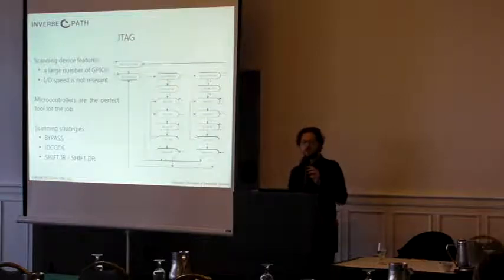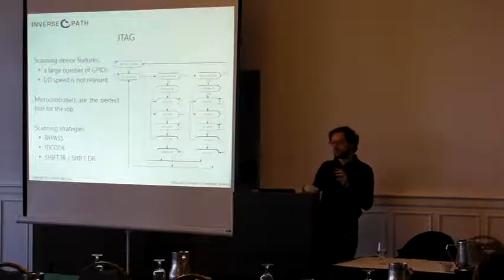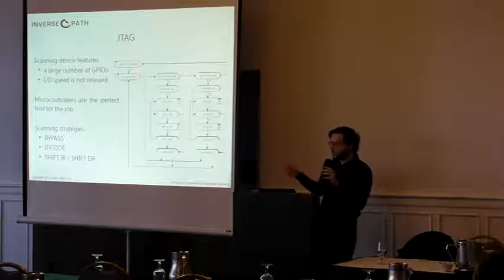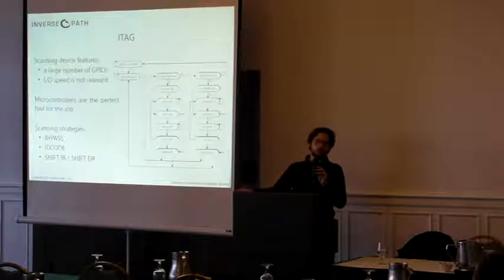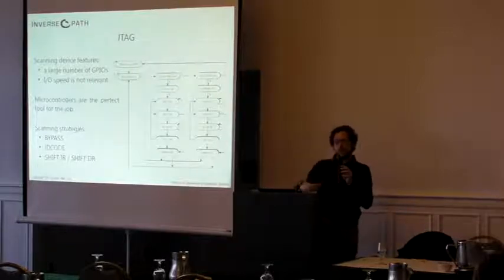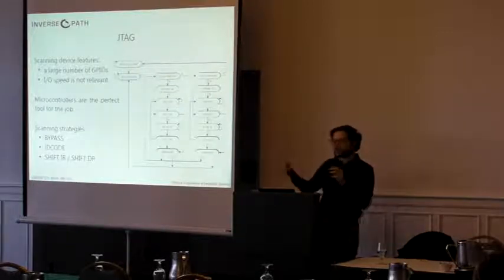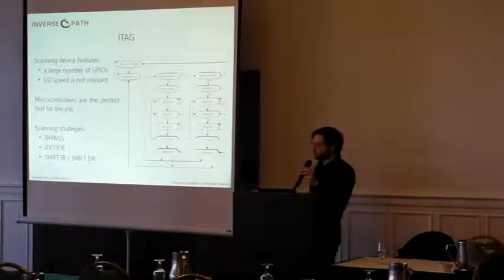For instance, the standard says that after you reset the device, it should always be either in bypass mode or ID code mode, which means that depending on the case, you can send some data on what you think is the data input, and then after one clock cycle, you can get some data out of the data output, which is either the same thing that you're sending on the data input in case of bypass, or it will be the ID code in case after reset you go into ID code.